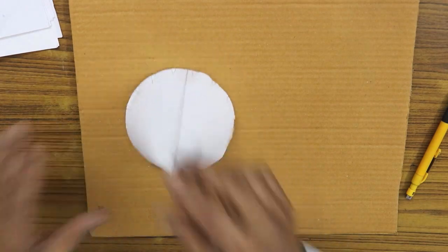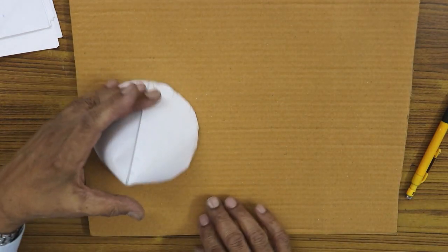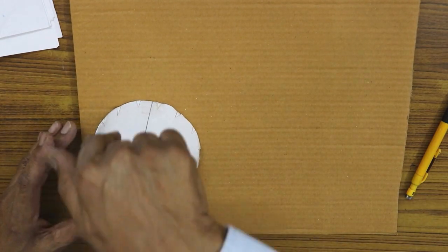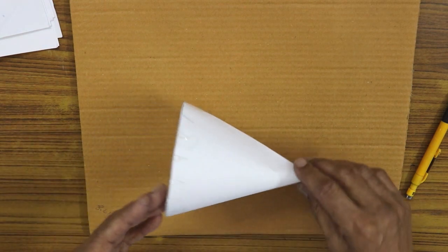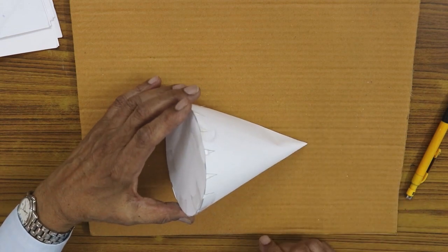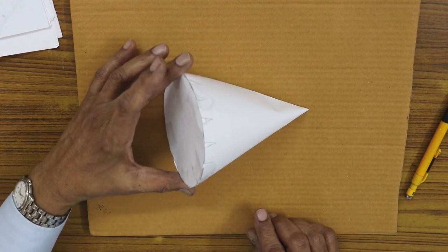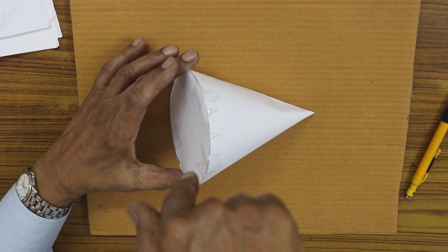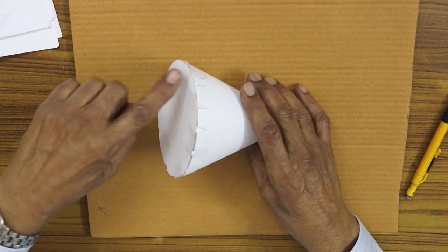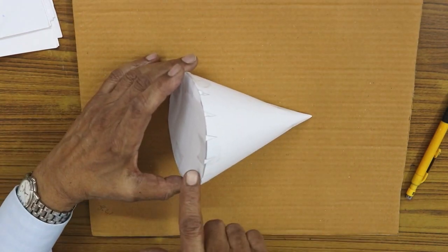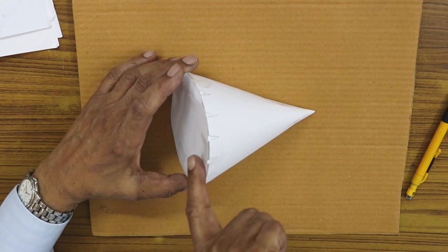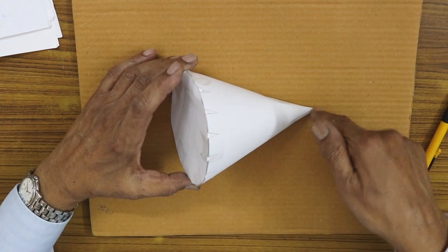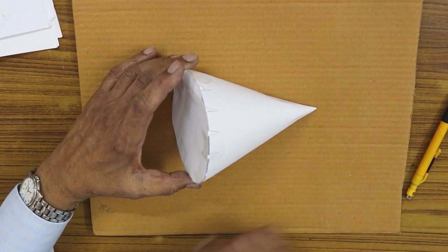We have here a cone. Initially, you draw the cone in this manner. Draw the top view and front view of the cone. The very first step: make the cone lie on the generator. In the top view, the circular base appears like an ellipse, and there is an apex point. Since the base is nearer than the apex, the base is fully seen, the ellipse is fully seen.